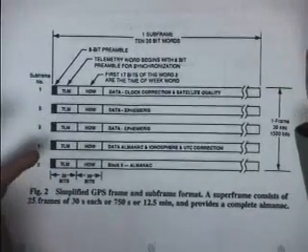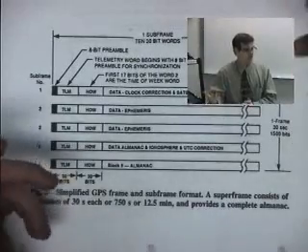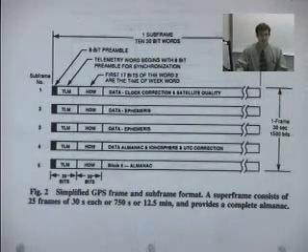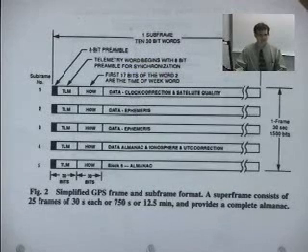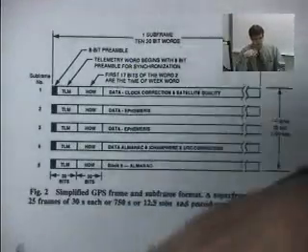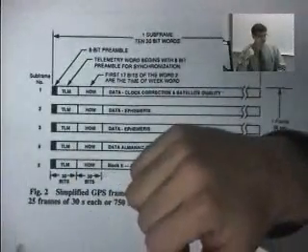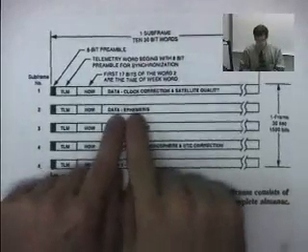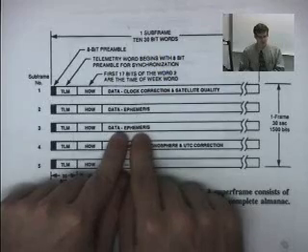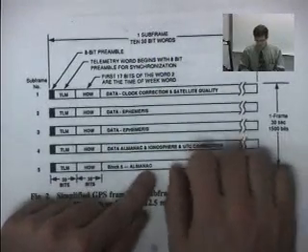And over time, unless you're just constantly exhausting station-keeping fuel, there'll be a little bit of a tug left or right and slow down, and enough to make a dent in your accuracy for GPS. Because remember, we're trying to pinpoint things within plus or minus several meters with GPS. A few meters of error in the position of a satellite that's zinging around the Earth is going to make a big difference in that calculation. And so ephemeris will tell you sort of how far out of whack that is. And you can use that in your corrections when you go to recompute your position estimates.